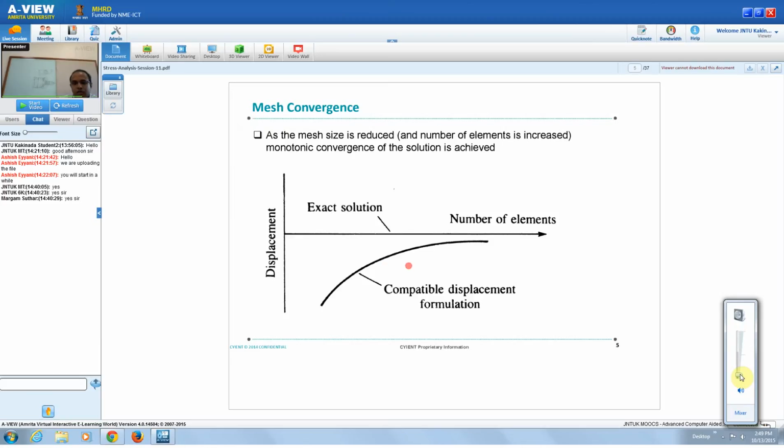When you do finite element modeling and run the analysis, the tool will calculate how much error is present in the finite element model. That is one approach. The second approach is doing iterations by changing the number of elements. These are the two methods we typically follow whenever we do finite element modeling.